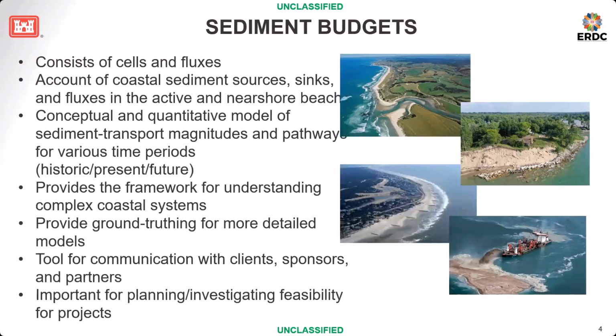So, sediment budgets as a whole. When we think of sediment budgets, I know everyone hears the word budget, and the first thing they think of is money. In this situation, we're just talking about budgeting where our sediment is, where it's coming from, and where it's going. These can be used for financial decisions at the O&M level, but for the most part, it's just where your sediment is, where you have your areas of accretion, where you have your areas of erosion. Your sediment budgets can be very rough in the resolution and the data quality, so we could be looking at maybe just a small inlet with 1 or 2 data sources just to get a general idea of where the sediment's going. We don't have to quantify it, just very conceptual.